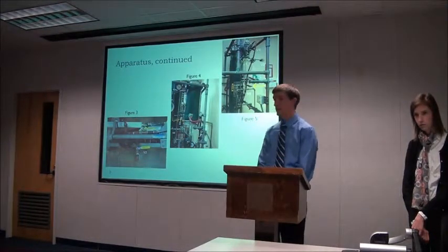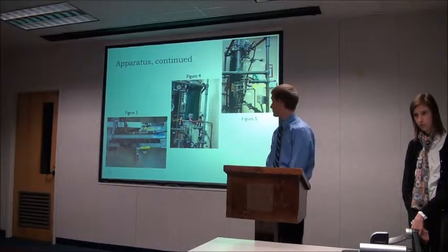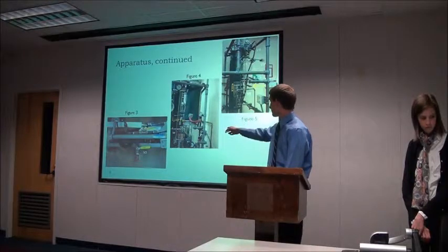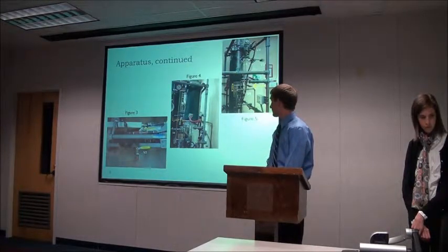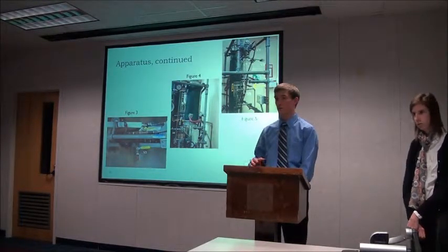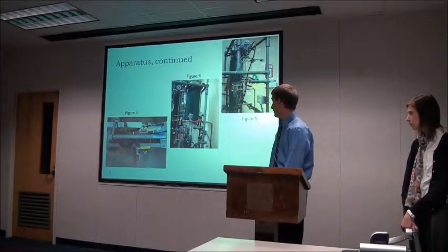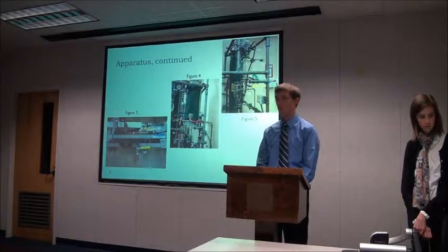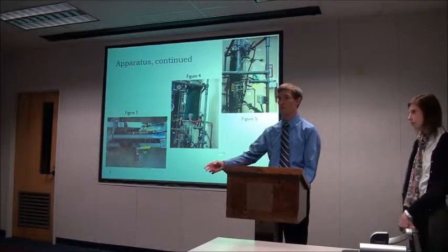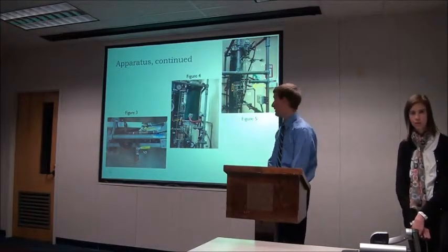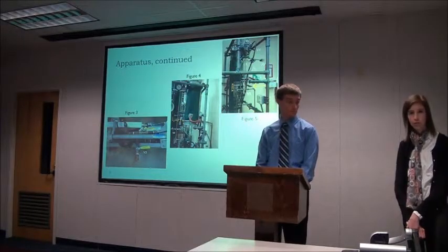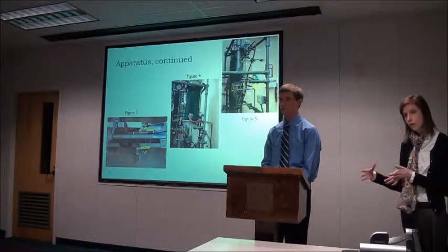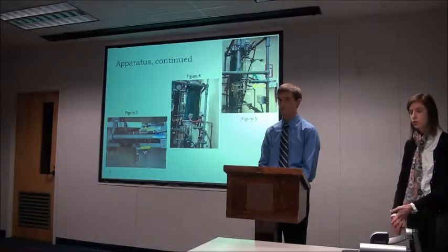In order to collect the liquid flow, what we would do is close valves 8 and 7 in figure 4. That way it would close off the system entirely, and we would open up valve 6, which would open the system to the atmosphere, and we could collect it through the tube coming out at the bottom. That was the relief valve. The purpose was to keep the rest of the equipment under vacuum while we were working on collecting our samples.